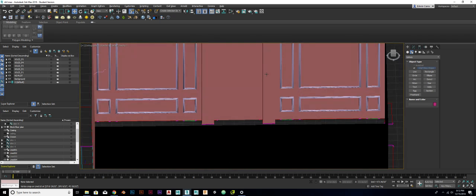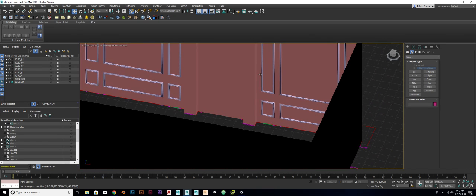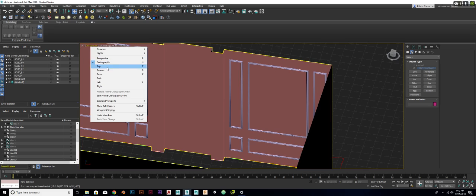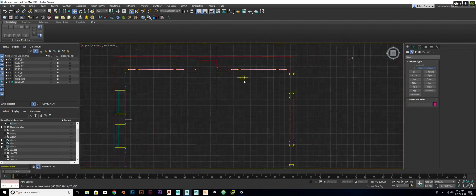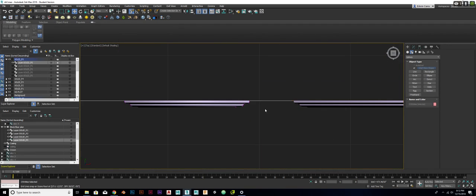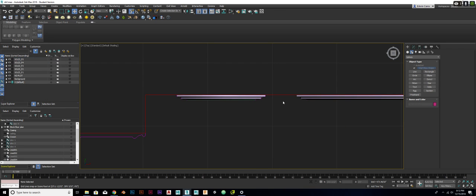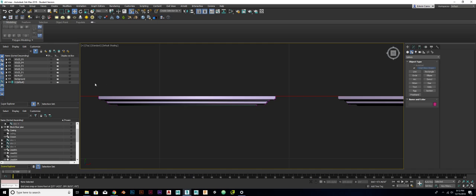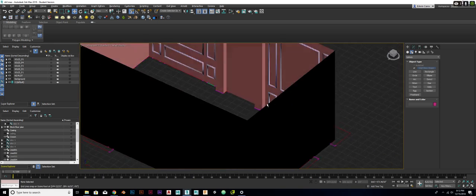Well, sorry, hold on, let's look at it from the top. If that red line right there, our wall, is going to be our veneered wall paneling, and this is going to be our solid wood applied molding that goes on top of that, then that panel needs to recess further back to suggest that this panel right here is behind this panel, and this is going over the two, so we need to be about here. We'll see in 3D if it looks too deep.